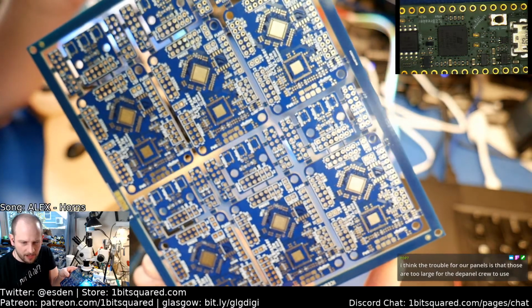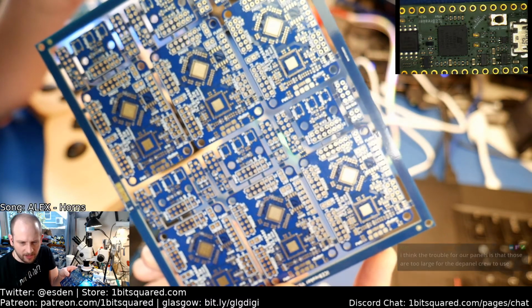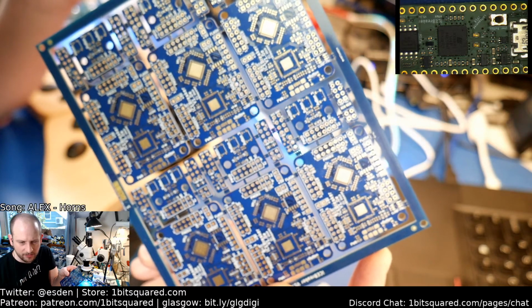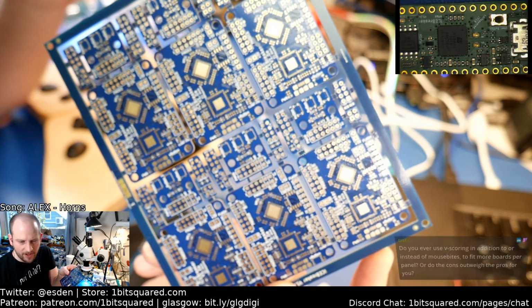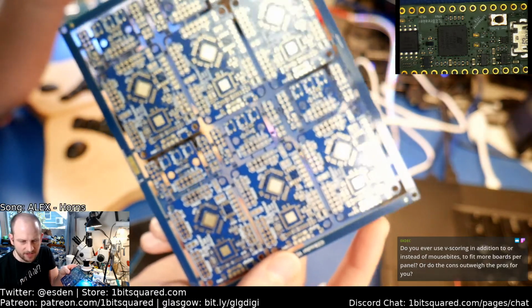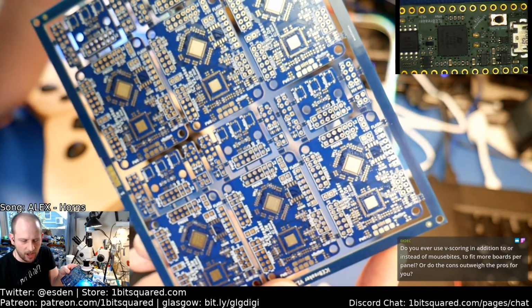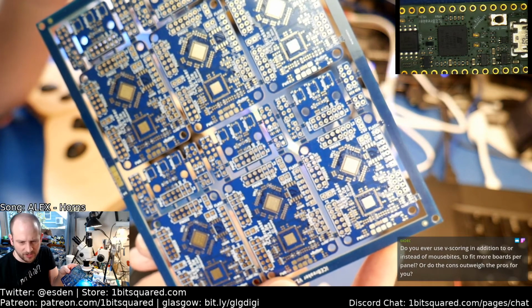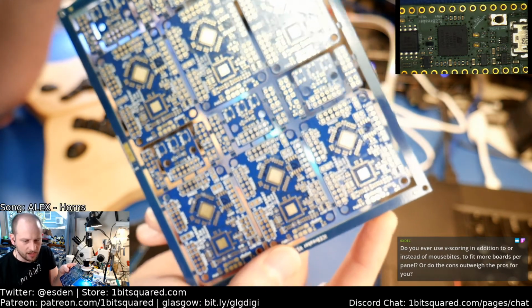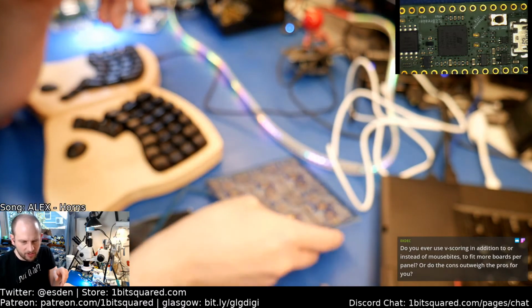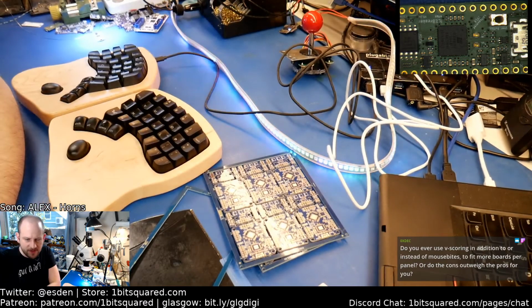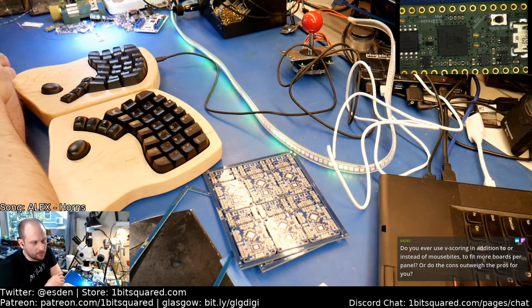So I used to use a 3mm gap between the boards and the tabs, because that's a more lenient routing bit size for the PCB manufacturer that is doing the routing. A lot of the PCB manufacturers, especially the low-cost ones, say it's a 2.5mm router bit. So they get pretty angry if you make the slots narrower than 2.5mm.